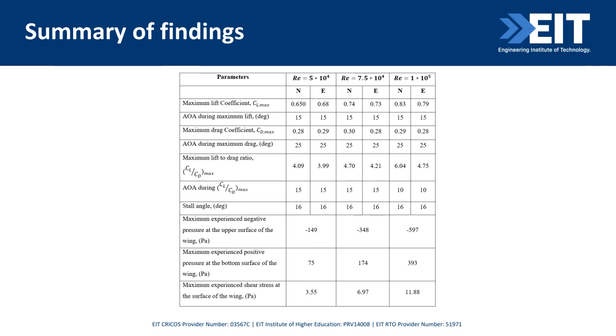At the end, we also see the effect of scaling. We see the result for the effect of Reynolds number. That was one thing, and also we see the effect of scaling. We scaled down the wing and we scaled up the wing, and see how much the result changes with scaling. For scaling, we change the aspect ratio, the chord length, the span length, everything.